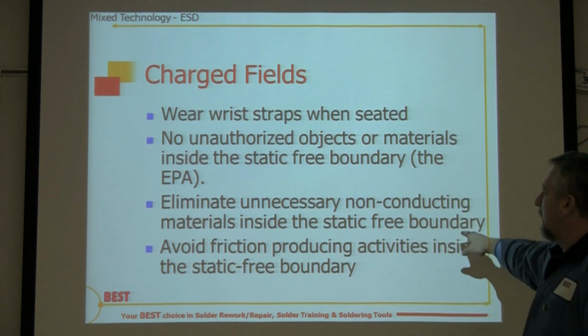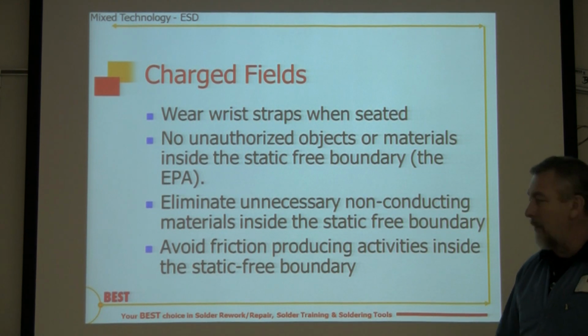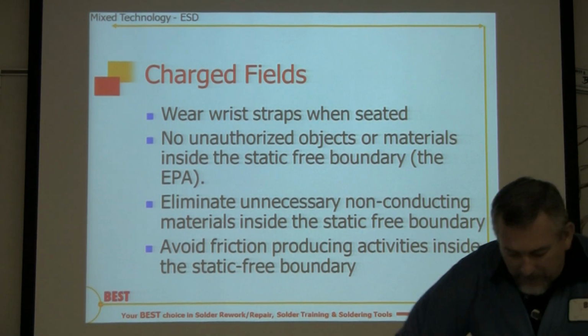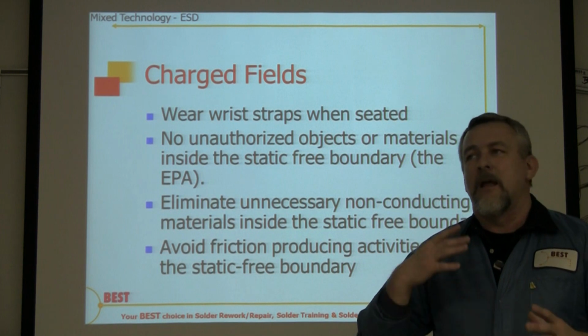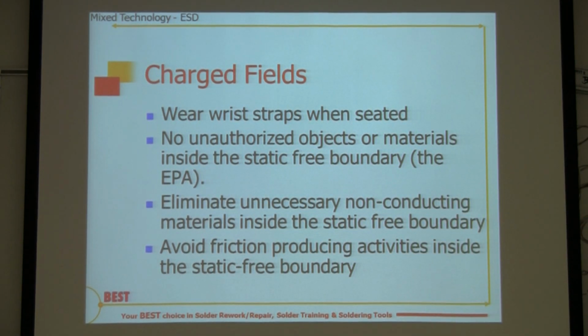Eliminate unnecessary non-conductive materials inside the static-free boundaries. If they don't need to be there, don't bring them in. Bottom line, avoid friction-producing activities: brushing your hair, wiping yourself off, stuff of this nature. These can cause static electricity, so let's try to prevent them from our work areas.